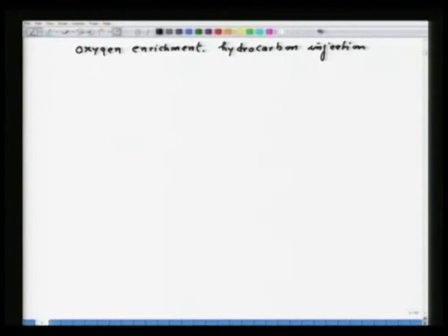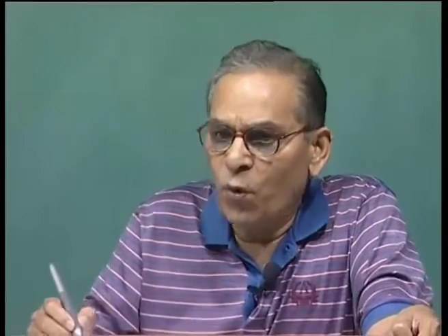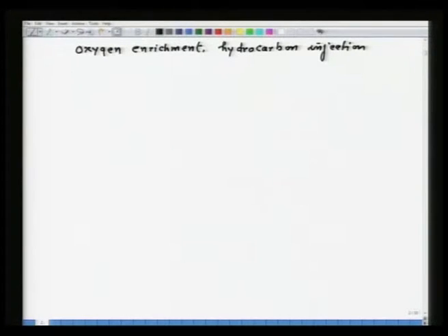As the burden descends, the gases travel up, and through the reaction between Fe2O3 and carbon of coke, or carbon monoxide which forms due to the reaction, the iron oxide gets reduced. As the burden descends, the carbon of the coke reacts with O2 at the tuyere level, because it is here that oxygen is available. So, what happens?